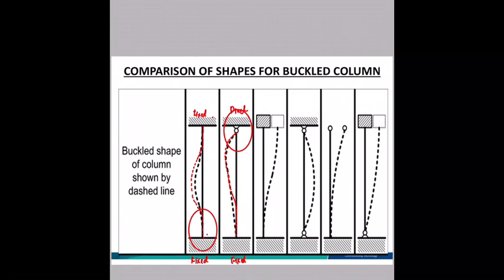And here is a free end, because it goes straight, and then near the free end, it goes up here. This one is pin connection. At the starting point of the pin connection, it will buckle like this. This one is also free fix, this one also pin. So the most common connections that we will analyze are fixed-fixed connection, pin-fix connection, free-fix connection, and pin-pin connection.